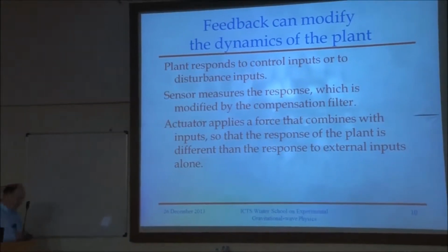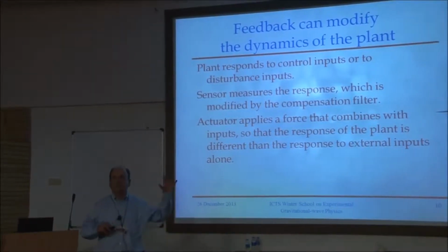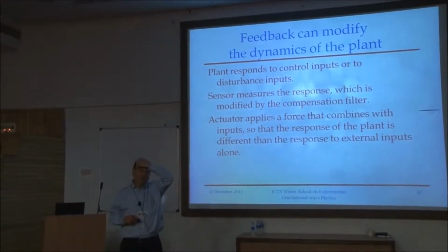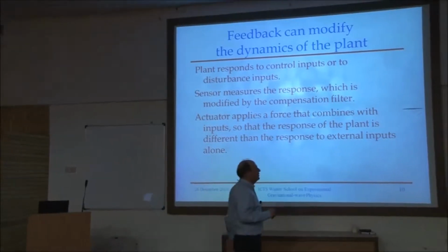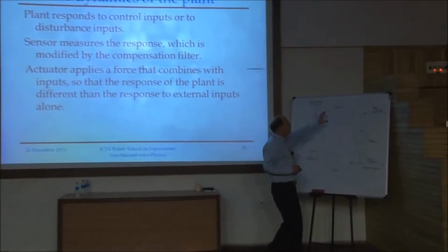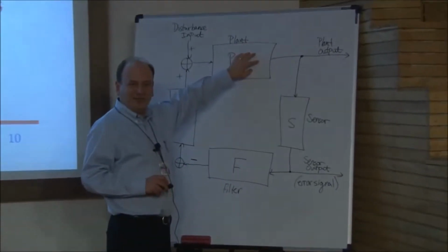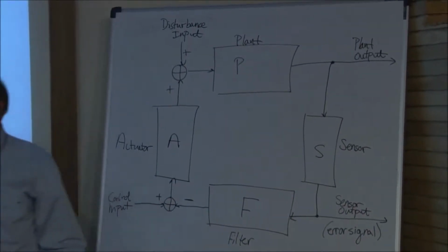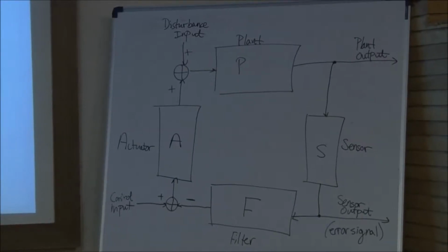Okay, another generic kind of use of feedback is to modify the dynamics, such as making it possible to live with a pendulum suspension that has a high Q. Somehow make that work. And there, the function is just to say, all right, if I look at the poles and zeros of this thing, I just want to move them in the complex plane to some other place that makes more sense for me. So that's something that's often worth doing.